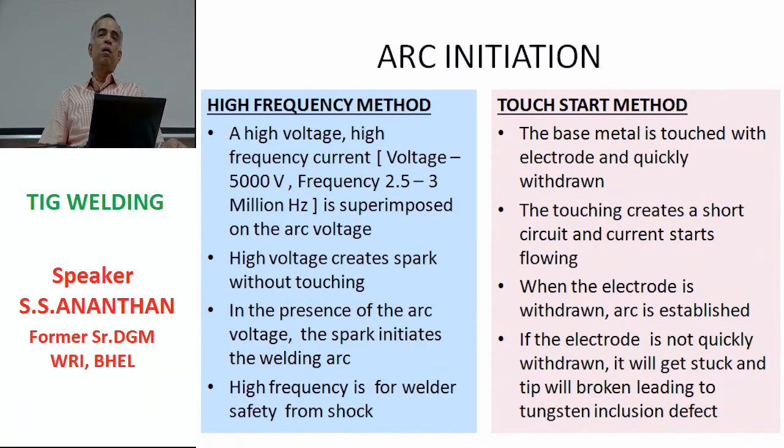Now one more caution for people who are using components like pacemakers for the heart or such electronic systems for health requirements: there is a possibility this high frequency unit can create a problem by inducing a voltage in this area. Similarly, if you have very sensitive instruments or robots or any other advanced electronic system nearby, there is a possibility that this will induce counter EMF or other voltages because of the high frequency nature. One has to be very careful, especially people having a pacemaker in the heart, who can have some problem, and they have to be very careful with these systems.